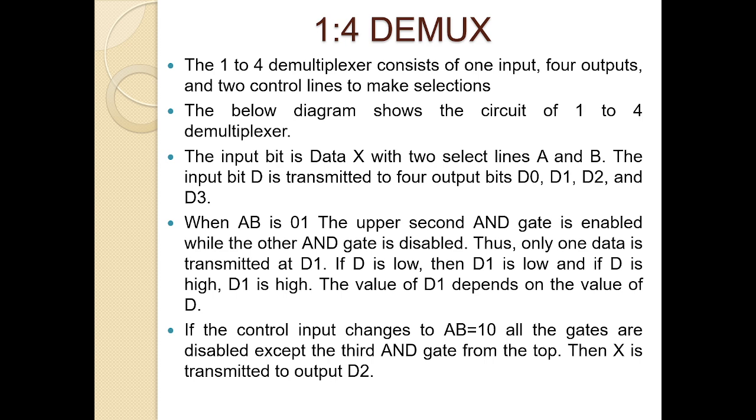It consists of one input, 4 outputs and 2 control lines to make the selections. The input bit is data X with 2 selection lines A and B. The outputs are D0, D1, D2 and D3.